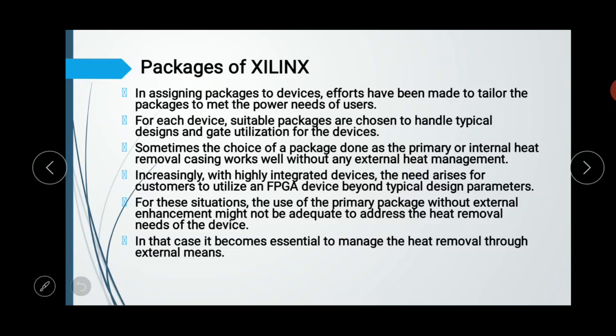In addition to performance considerations, there is also the need to satisfy system reliability objectives by operating at a low temperature. So, failure mechanisms and the failure rate of devices have an exponential dependence on the device's operating temperature. Thus, the control of the package and, by extension, device temperature is essential to ensure product reliability.